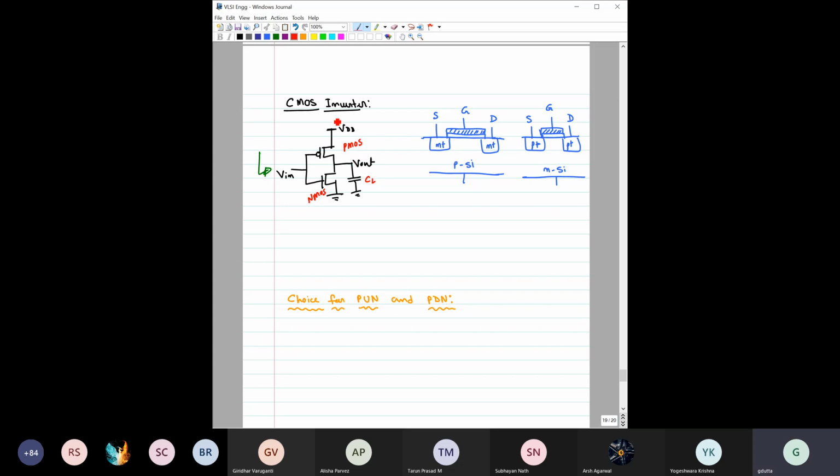So far so good. So here, this is drain, this is source, this is gate, right? For this transistor, this is the gate. So what would be this terminal, source or drain? For PMOS, yes, it is source, it is drain. So the same current ID has to flow through both these transistors, right? I am saying the DC current, obviously. The DC current has to flow through both the transistors, if there is any.